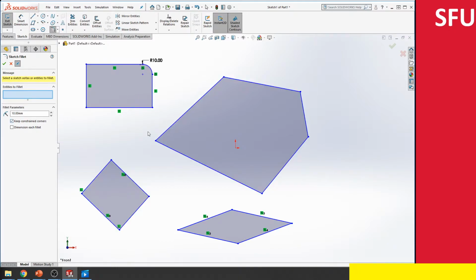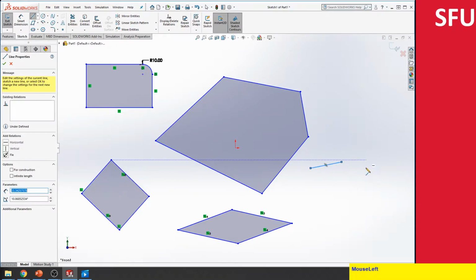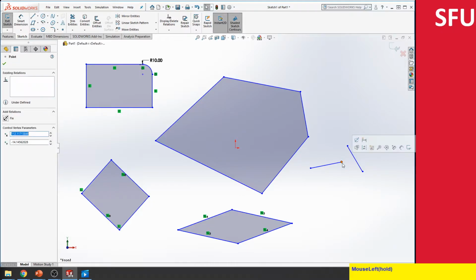So these are the sketches we have. Imagine right now, let's look at the trim example. Imagine I created one line over here, and then I happen to create another line over here, and then I notice that I want to get this line all the way here. One way to do it is to grab hold of this point and extend it all the way. There's an issue with doing that: you might actually change the orientation of a line.